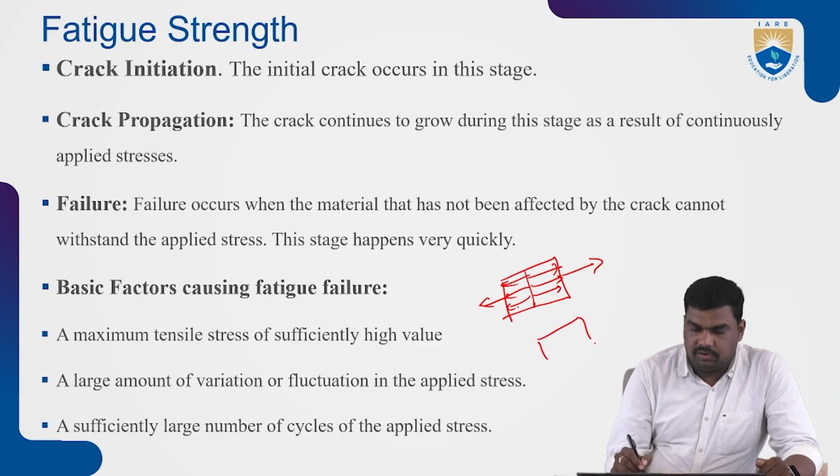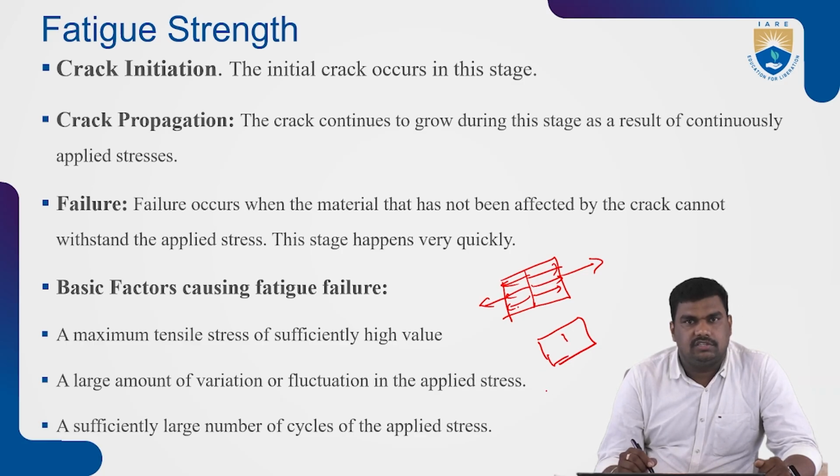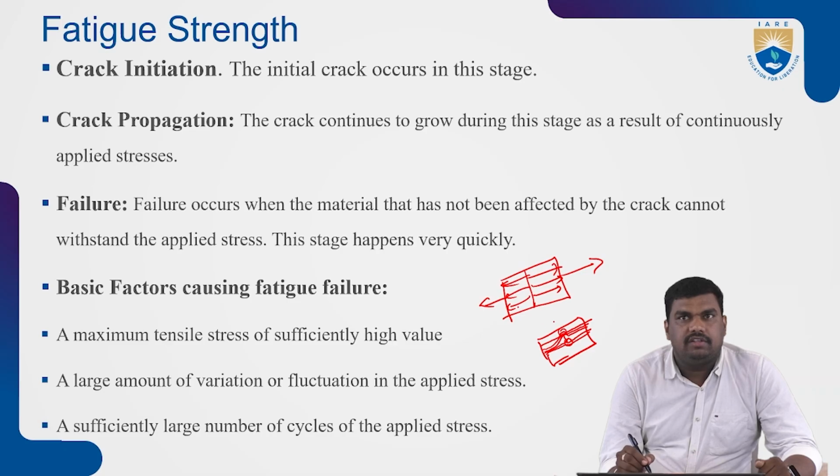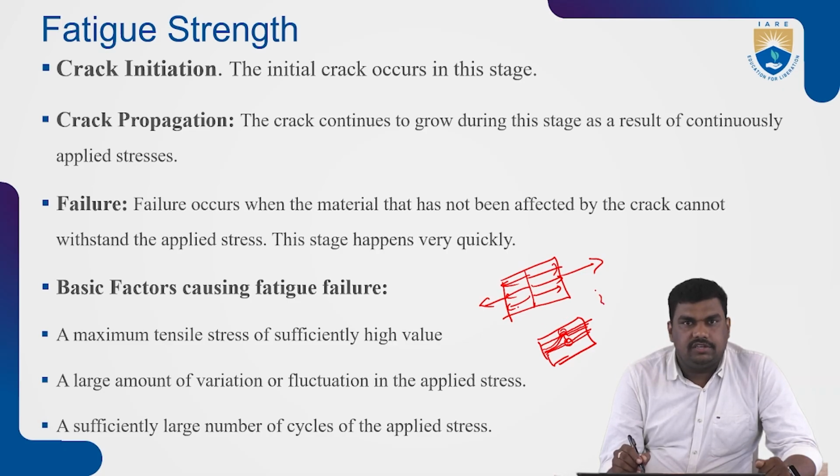Now in the same surface, if one small crack or scratch or undulation is formed, when this stress comes it creates a stress concentration over the tip area. At the tip it creates more stress concentration. This is the initiation of the crack, and due to the stress concentration at the tip, the crack will propagate further.